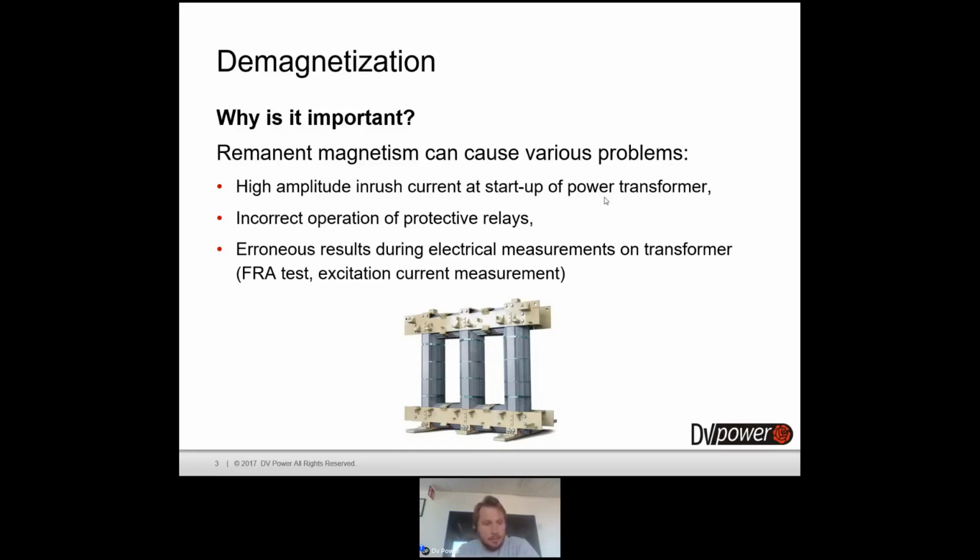The problem in the field is usually that you don't have a lot of time, and you start thinking, what is happening, maybe there is a fault in the transformer, and there is analysis of that. But the transformer is just magnetized. Magnetization is not any kind of failure in the transformer. It's a normal, natural process in ferromagnetic material.